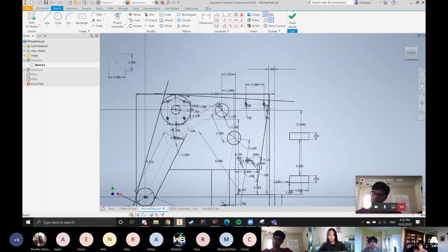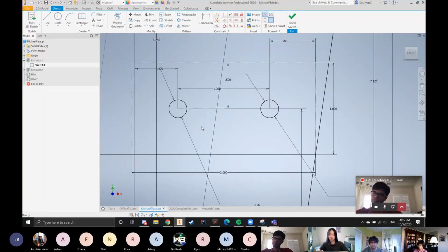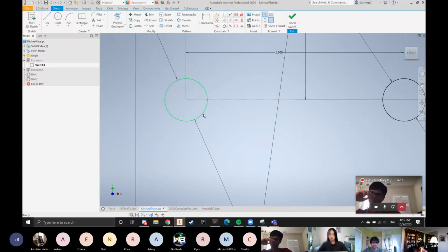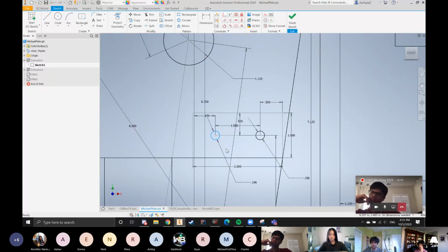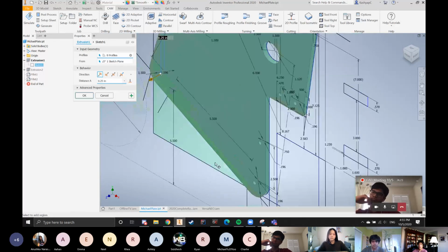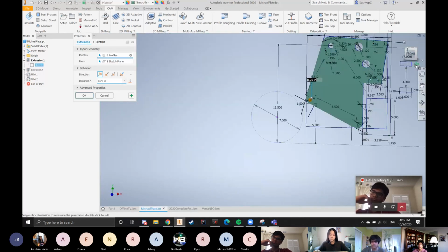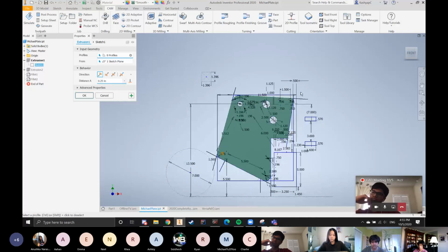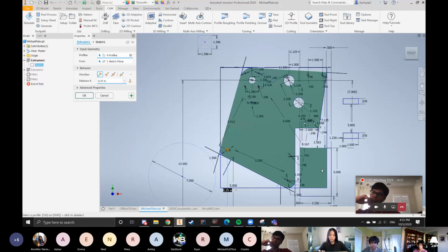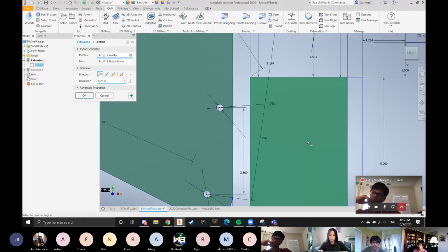And then also things like mounting holes. Mounting holes are just holes for screws, and that's literally just a circle, and then you don't extrude that circle. So if I go into my extrusion menu, I know we're probably going to talk more about extrusion next time. You'll see the only part I extruded was the part that I intended to be the plate. I could extrude this too, but I know that's part of my bumper, so I don't want to extrude that.